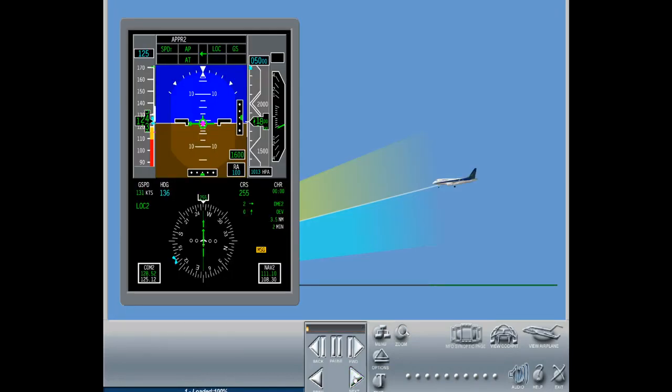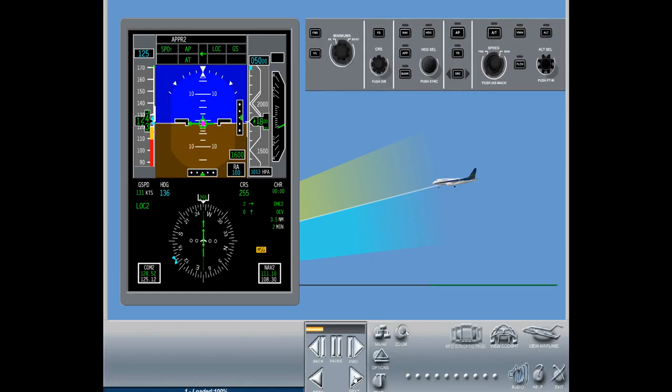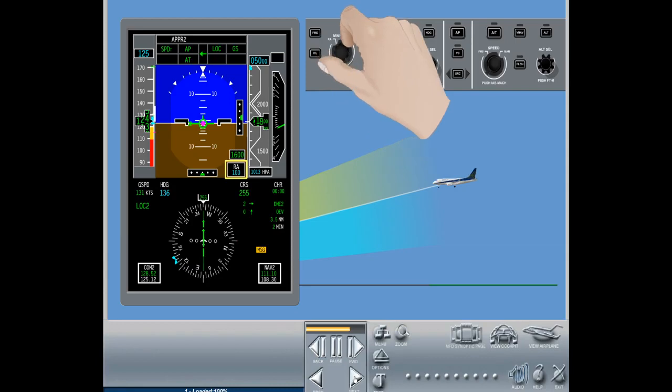During execution of an ILS approach, the autopilot approach status annunciator displays the current status of the system and alerts whether the intended approach matches the system capabilities. When ILS modes are requested via the APP button, the system arms for the highest capability available, and the RA Baro selector and RA minimum setting inform the system of the intended approach. For Cat 1, set the RA Baro selector to Baro, both sides. For Cat 2, set both RA Baro selectors to RA and adjust minimums to 80 feet or above.